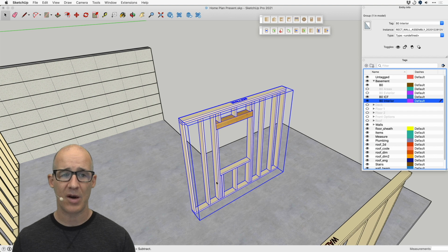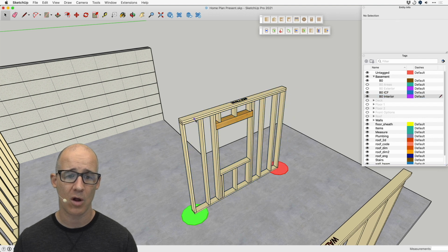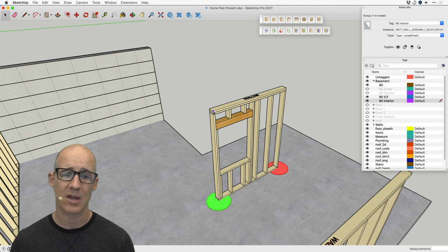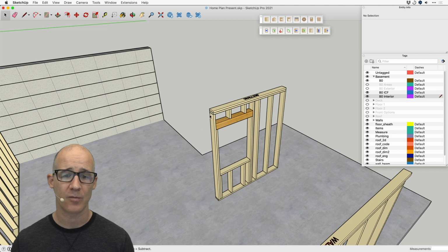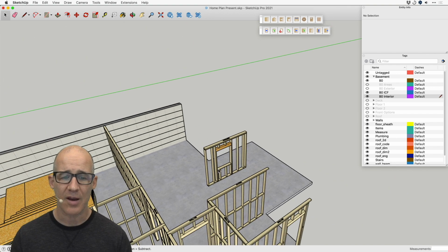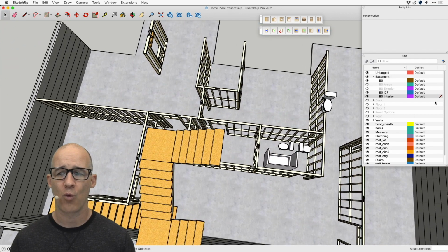The only other thing that I've been able to do a couple times is actually just resize the wall, where I'll click this tool and then I'll click the wall. It's a triple click situation. I'll resize the wall and then do that same process again and just move the wall back to where it needs to be. Click once, click the second time, click the starting point, drag it out, and reconnect the wall. That is what I have found out to be the case, such that when you're working with layers, it resets it. And it's this process I just did.